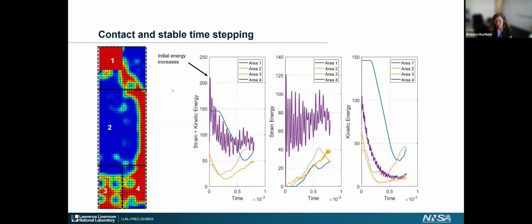There's a couple of different things. One thing we could do is resize our stable time step, but a couple of back of the envelope calculations showed us it would have had to have been a couple of orders of magnitude smaller, which means that instead of running a couple of thousand time steps, we're now running tens or hundreds of thousands of time steps, which we can do, but we'd like to avoid doing just for that bottom boundary condition if we can help it.